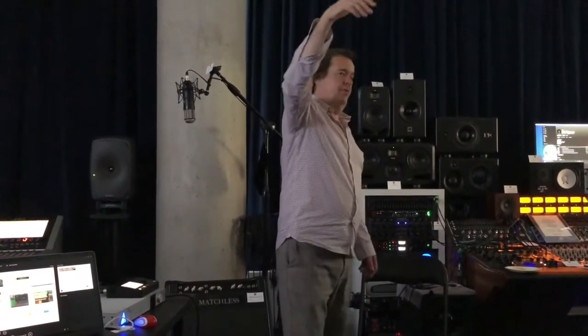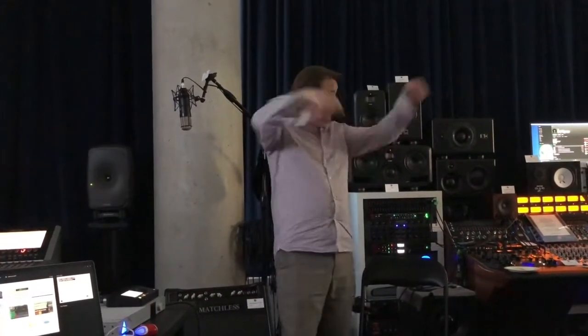Okay, and you have redundancy as well if you wish to, for a cheap price compared to MADI, AES/EBU, analog with big cables and all of that. So flexibility in all of this. So you have one big device on the stage, where you have your XYZ number of 20 microphones or whatever, and you just have one network cable coming to you, or two if you want redundancy, and you have everything, all the traffic going on those networks.